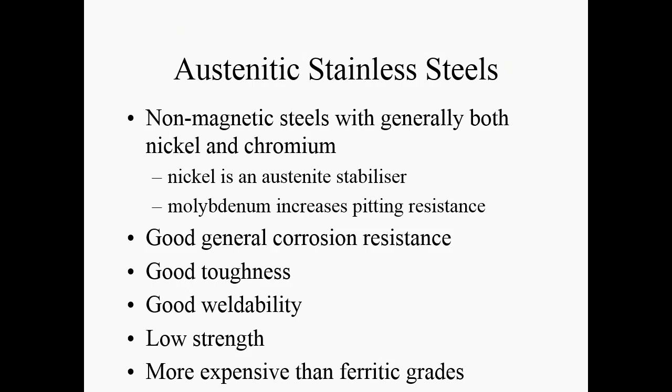316 stainless steel, which is used in medical and chemical applications, has 4% molybdenum added to that 304. So you can already see that just in the same material, you can have different grades which are suitable for different applications. And there are stabilised and unstabilised versions of these steels, which may or may not have a percent of titanium or niobium added to them. And again, that depends upon whether you want the steel to be weldable or not. So there's a whole range of things you have to consider.